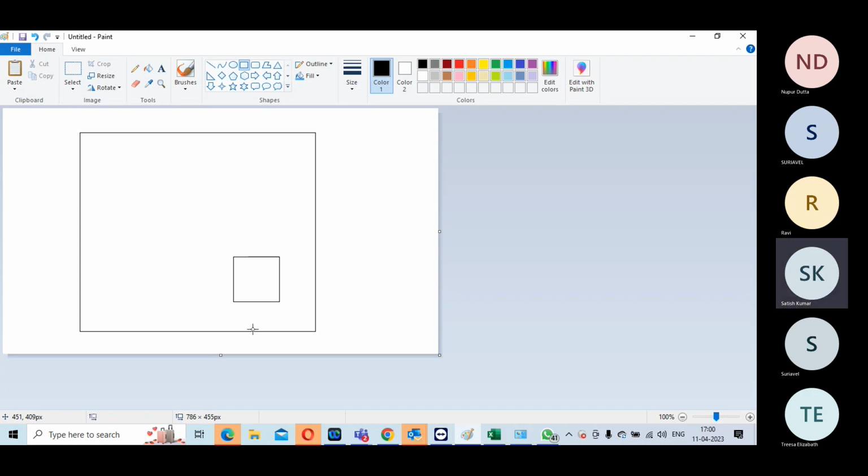Sir, we can touch the metal layer. For clock pulling, a higher metal layer is not required, you may have to do routing, tap the previous cell and connect that net. Clock pull means early. Clock pushing is where you have to add one more buffer. Clock pushing is not possible. Clock pulling is possible. That means early. You have to connect to the previous net.